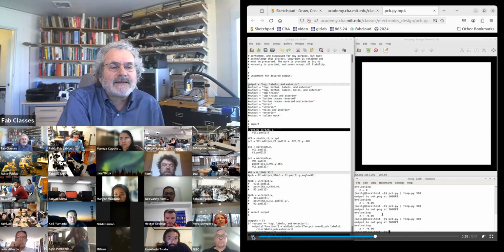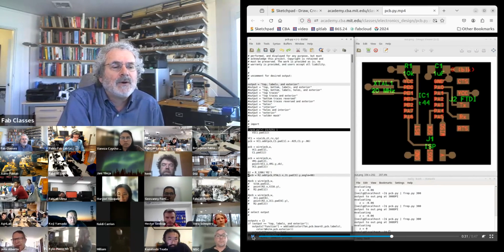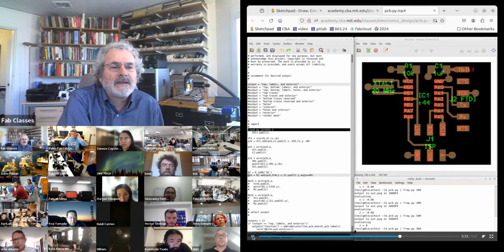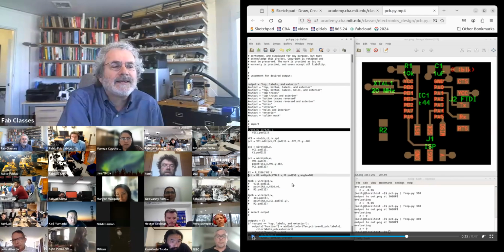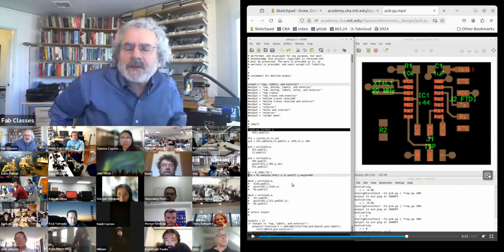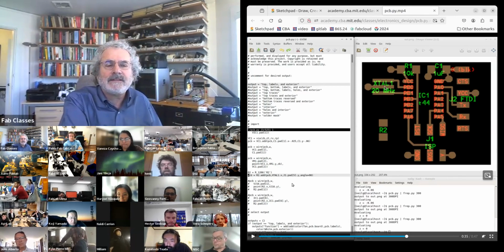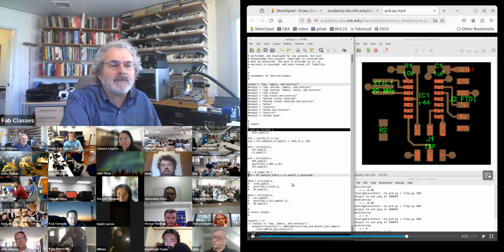And then to edit it, I'm going to add a component. And rather than clicking and dragging, I say I want it under the crystal and next to the connector. What that means is later, if I move the crystal or the connector, these know their relationship, and so they move together.